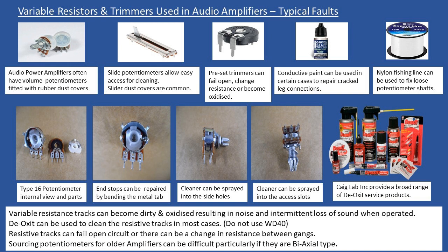So don't just spray the DeoxIT in once. You might need to do it multiple times and leave it a few minutes, but in most cases you should be able to recover the potentiometer so you no longer have any noise. But not in all cases. Sometimes you do have to replace it if it's physically damaged.